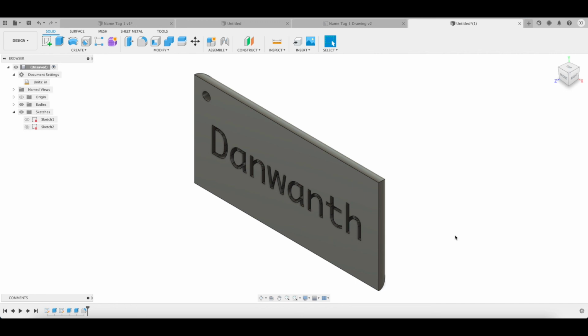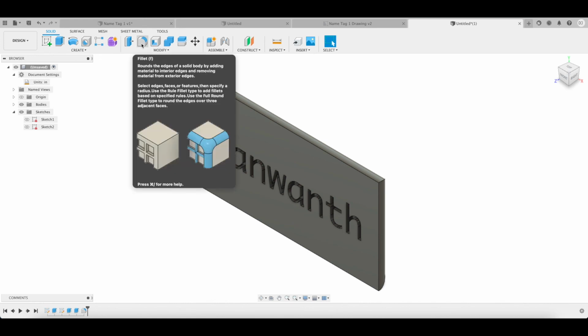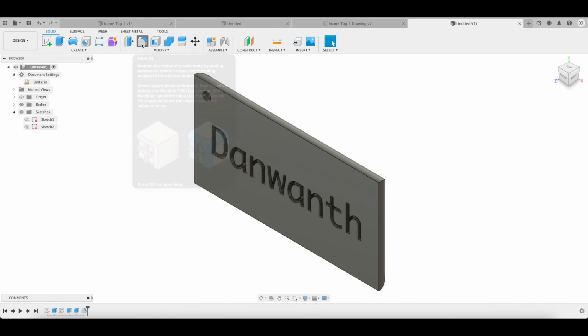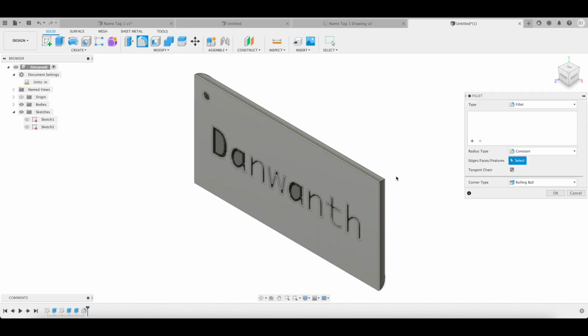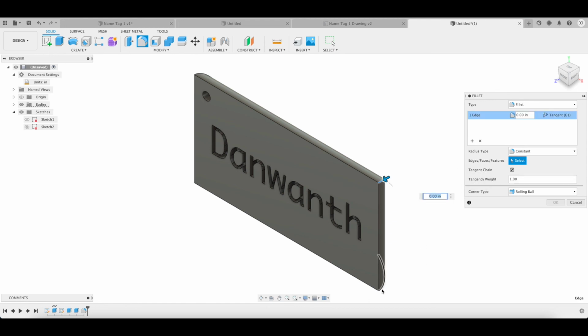We can apply more fillets. So let's apply 2 more fillets. We're going to apply 1 to the corners after we've applied the third. We're going to apply 1 to these edges right here. There are some sharp edges over here, we don't really want that. We're going to apply 1 to these.